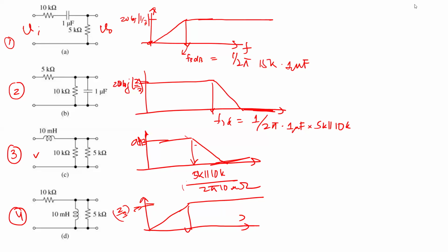There is a pole frequency which is R over L, because again, if you write the whole transfer function with SL, you're going to get K over S plus alpha, right? I think everyone understands that, right? If you substitute SL and write the equation, you're going to get the low pass filter. I'm just intuitively showing you why it is a low pass filter.